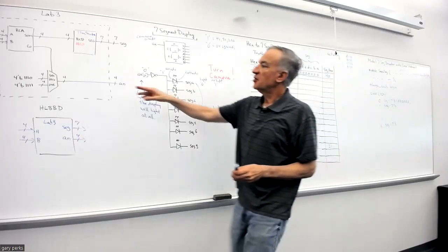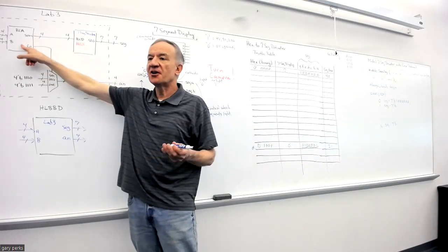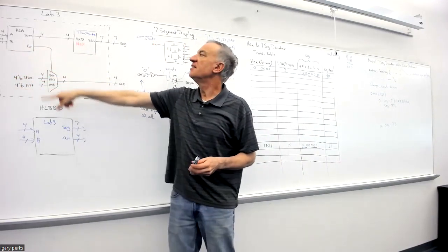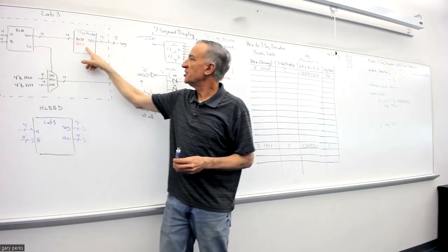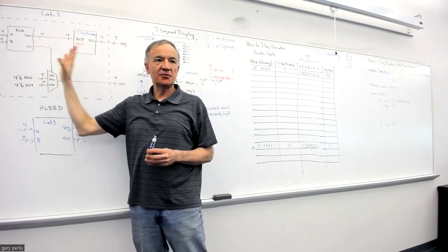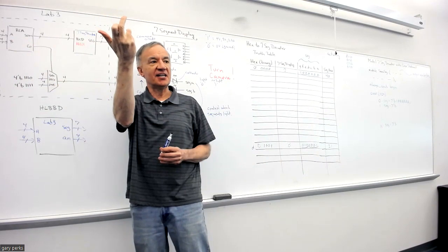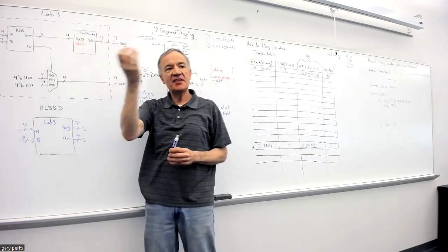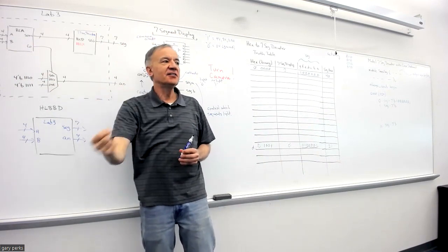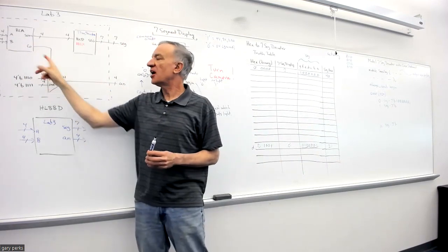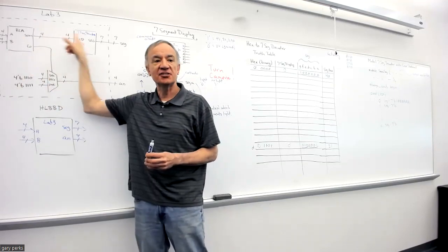And then once you have simulated this, again, I assume you've already simulated that for last week, then you have to test the whole thing. Right? Because once you have these low-level blocks done, now you're going to need a structural design, right? Just like you had that structural design that connected up the adders into a ripple carry adder. Once you're done with these blocks, now you need another design source, a structural design that makes the connections between these.